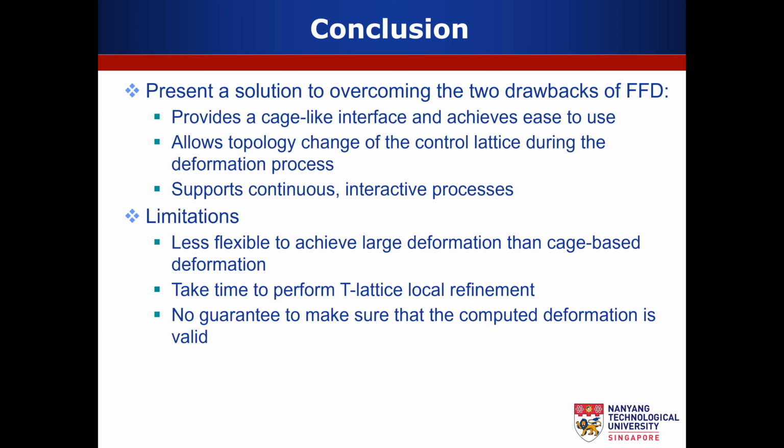However, the proposed method also has some limitations. Firstly, it is less flexible in achieving large deformation than cage-based methods. Secondly, if we start with a very coarse mesh, it will take time to perform the T-spline volume local refinement algorithm to create a dense proxy. Thirdly, our method does not provide limits on the deformation or a guarantee, such as an as-rigid-as-possible minimization procedure, to make sure that the computed deformation is valid.